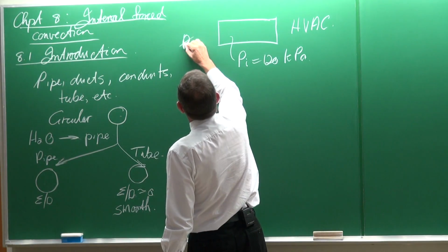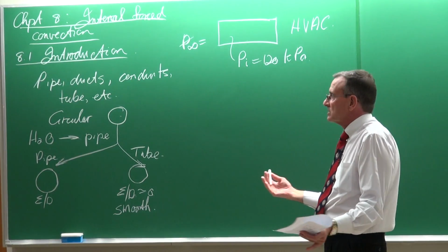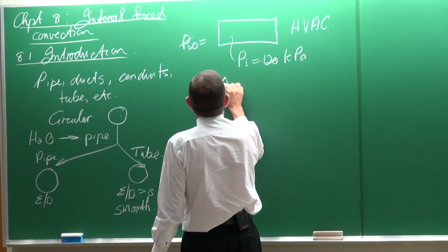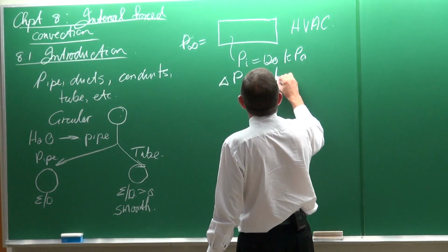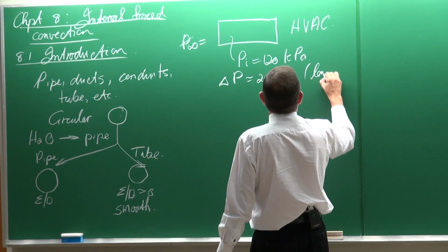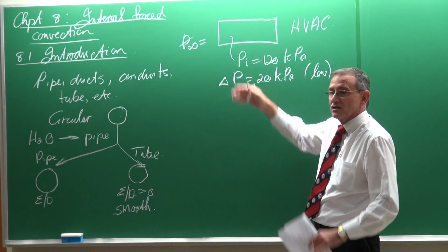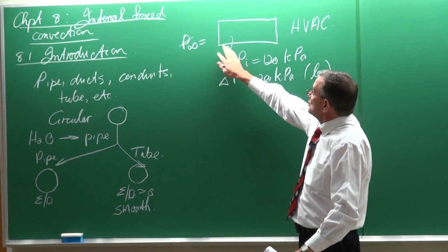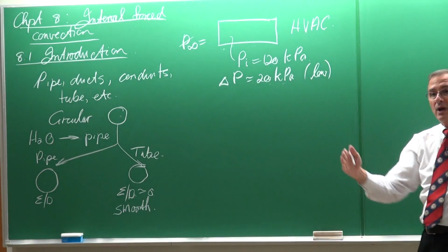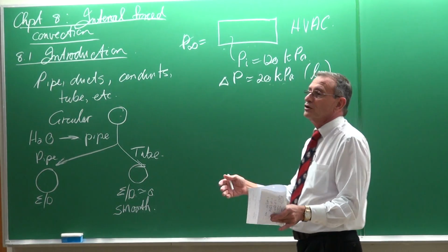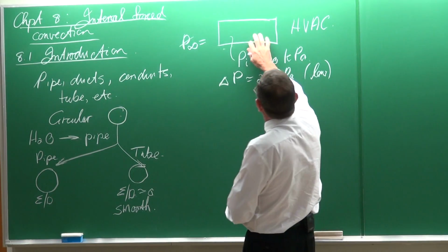Normally, the pressure on the inside would be something like 120 kPa, while the pressure on the outside would typically be atmospheric, 100 kPa or something like that. So therefore the pressure difference over the wall is in the order of about 20 kPa, which is very low. And although it is that low, you must remember these ducts are usually very large. So the surface areas are very large, and if you've got 20 kPa working on 1 square meter, it is 20,000 newtons of force that you actually have on that area there.